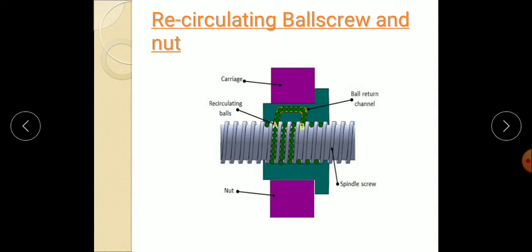When the screw shaft is rotating, the steel ball at point A travels in 3 turns on the screw groove. So this is the groove, rolling around the grooves of the screw shaft, and the ball nut eventually reaches point B. Then the ball is forced to change its pathway at the tip of a tube.